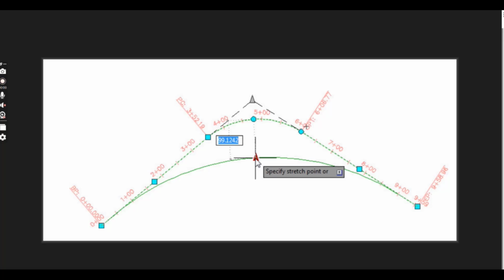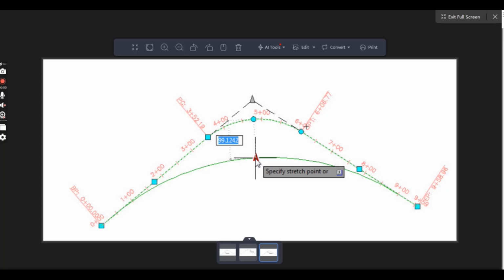As a note, an alignment that is created from a polyline will be defined by free segments only if the segments before and after an arc object are tangent. Otherwise, the segment will be fixed as mentioned previously.